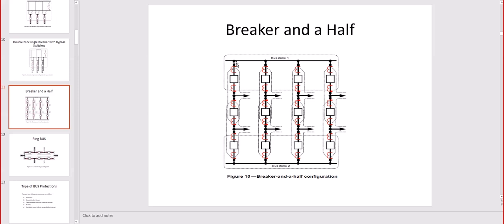You hear that in our substations, in our switchyard also, people talking about diagonal breakers and so on. It's just the breaker that makes a link between one bus and another. So in a simplified model, you may not have the middle breaker. Here you have 3 breakers. You may only have 2, and if you have just 2 feeders, basically you have 2 breakers and the feeder. So a lot of the distribution substations are like that in Darlington. For the 44 kilovolts distribution, almost everything is a breaker and a half, a simplified version.